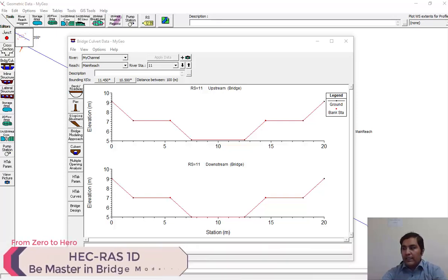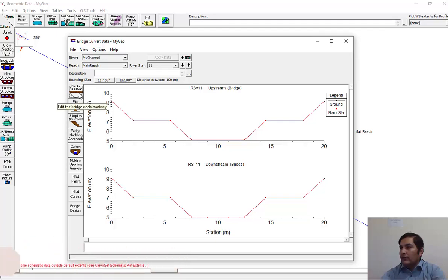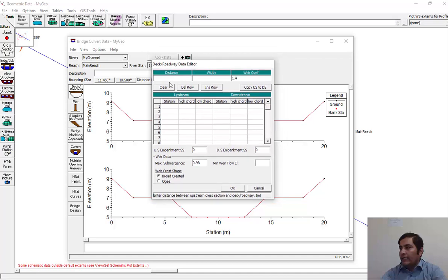Okay, let's continue the bridge modeling. I select deck roadway, and in this part you should enter the distance between the upstream cross section and the deck. Okay, let's assume that this distance is about...